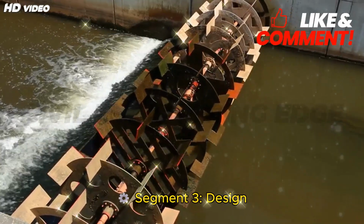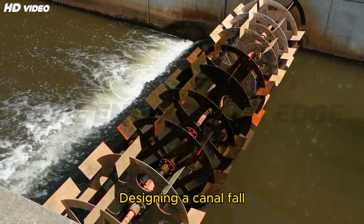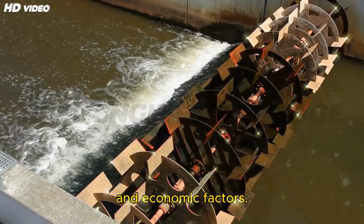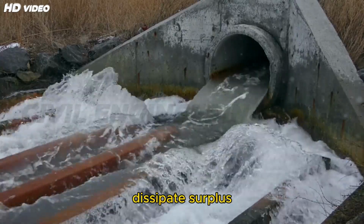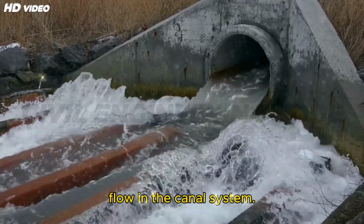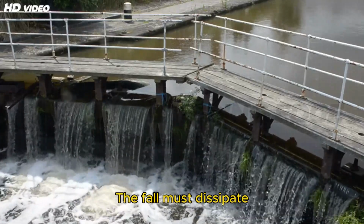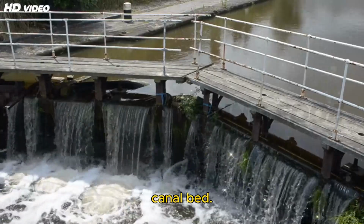Segment 3. Design principles of various types of falls. Designing a canal fall requires careful consideration of hydraulic, structural, and economic factors. The core design objective is to dissipate surplus energy and maintain a safe and uniform water flow in the canal system. Key design principles include: 1. Hydraulic efficiency. The fall must dissipate energy efficiently to prevent scouring of the canal bed.